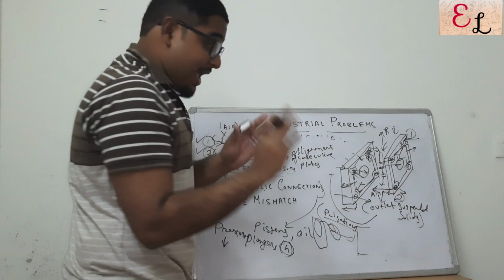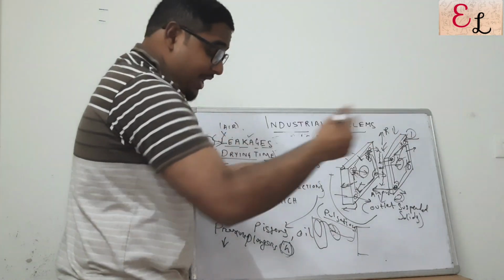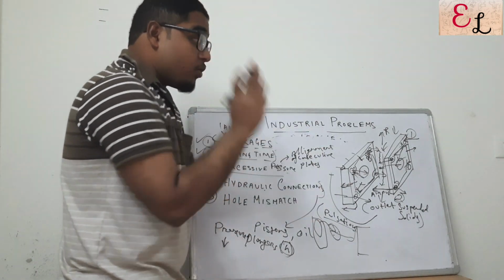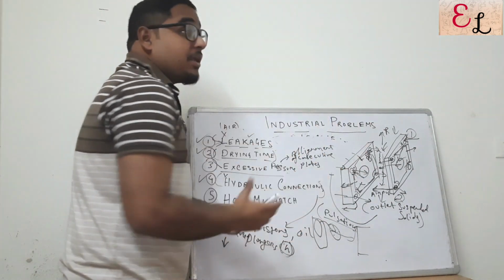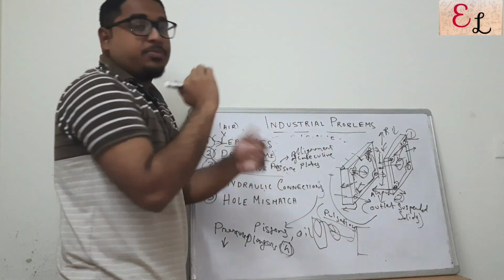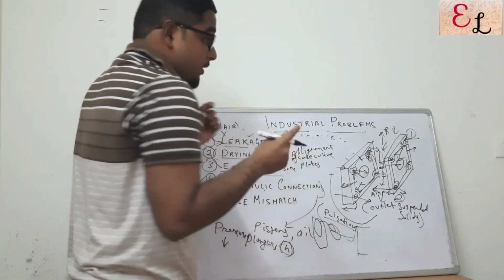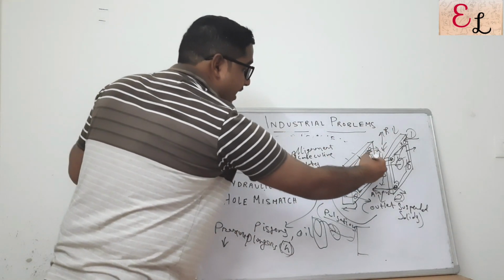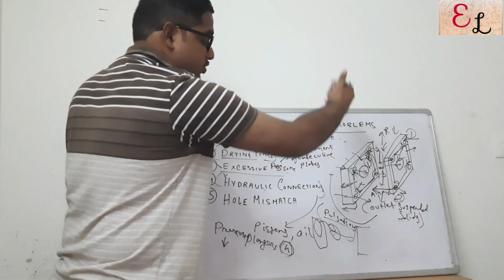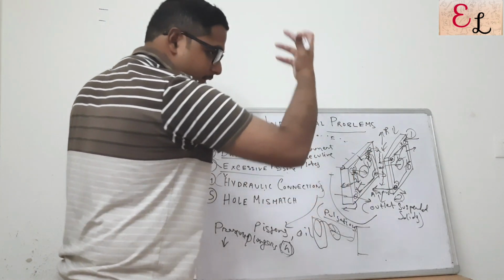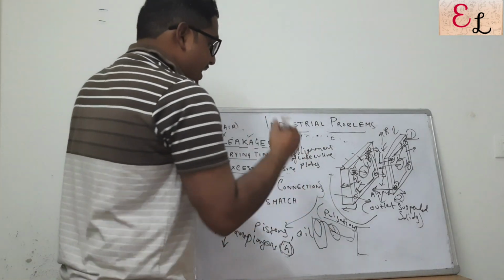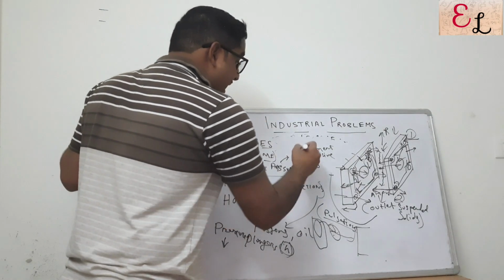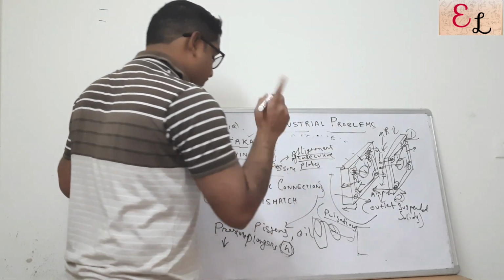plates are having the drain points on the left side or on the right side simultaneously, then that's a big problem, because that creates pressure or cake deposition only on one side and the outlet is taking place only through one side, and even distribution of pressure is not occurring. Because of this, the cloths over time tend to tear or get heavier from that side and the cake deposition is more here, so it tends to tear off from there and the cloth damage is significant. So to avoid that, alignment should be proper. Alignment of consecutive plates should be proper.